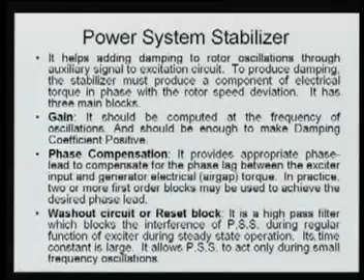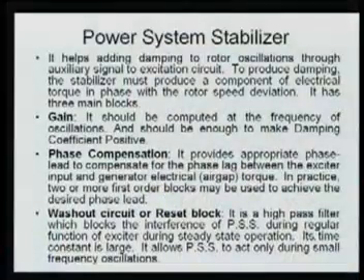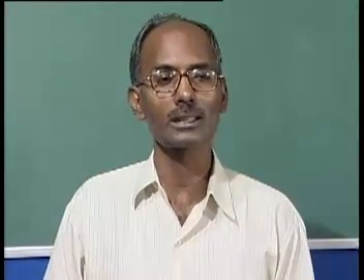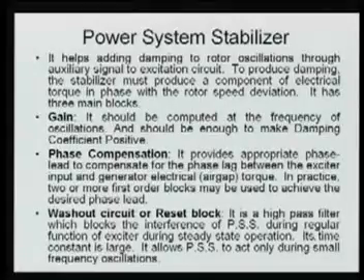In the previous lecture, I was drawing the DC excitation type 1, where I said there will be one auxiliary signal coming from the power system stabilizer. That signal is adding some extra signal to your excitation system. To produce damping, the stabilizer must produce a component of electrical torque in phase with the rotor speed deviation.